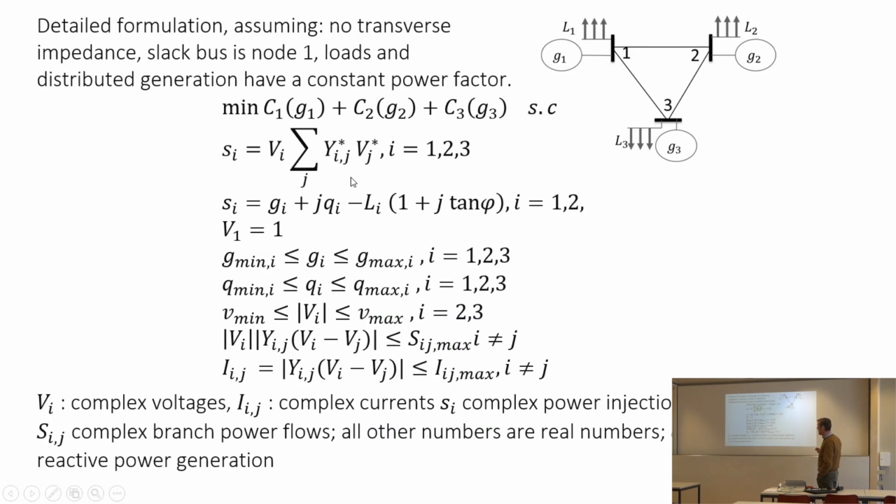And by the admittance matrix computation, this depends linearly on the voltage at all the buses here. Right? So the current that flows on line 1, 2 is equal to Y12 times V2, the injected current. Sorry. So this is the equation that we will have for the injected power here, which is also equal by the power balance equation.